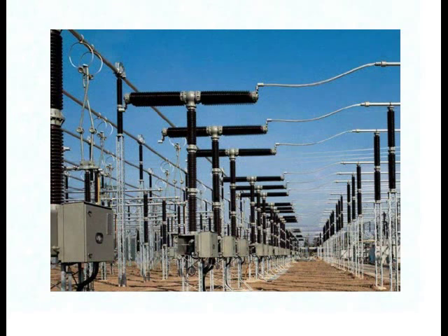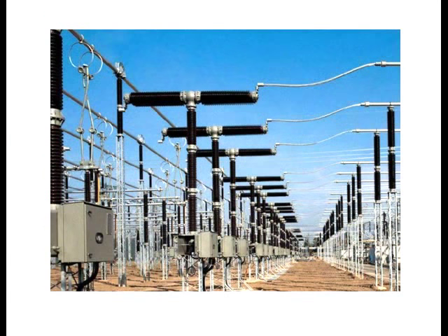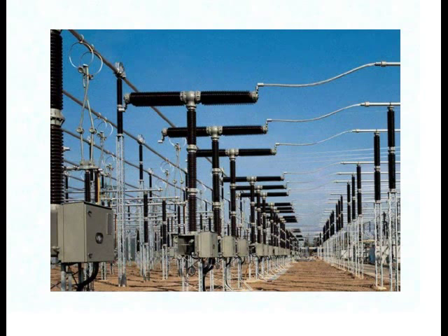This is the picture of a circuit breaker. There is no visible rotating part because everything is done inside the circuit breaker. As in an isolator, we can see the movable part moving while it is in operation, but in a circuit breaker you cannot see anything from outside. Also remember what I have said, that isolators are offload devices and circuit breakers are onload devices.